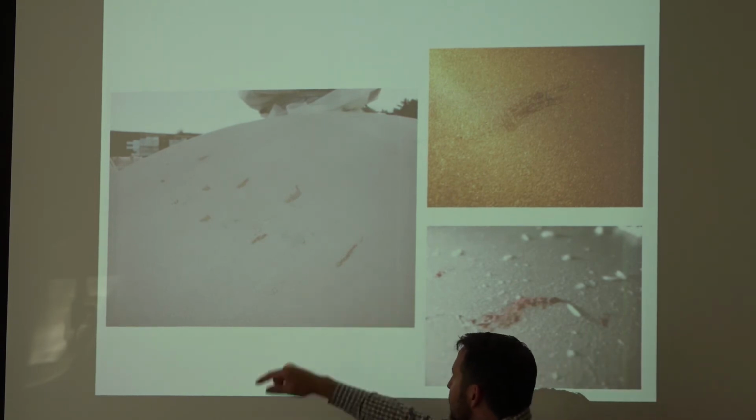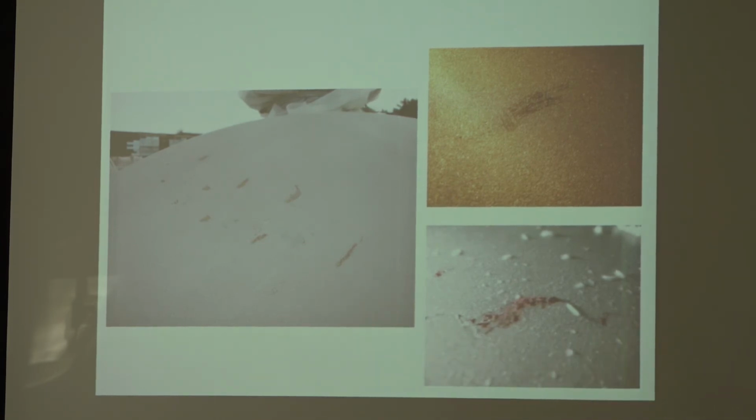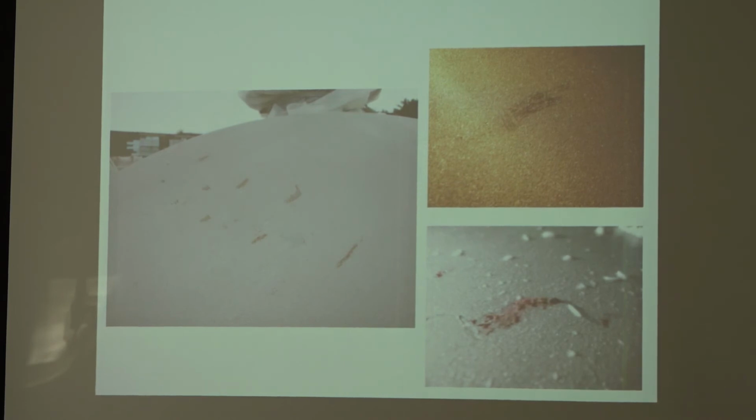So I mentioned that you don't want to use regular steel as tools to work on stainless. What you see here is a very expensive pressure vessel that's got rust on it. The customer called in saying, hey, this is not supposed to happen. The only thing they did at the shop is they were using regular chains to lift it. So it smeared some regular steel on the surface, and that's what caused it to rust.